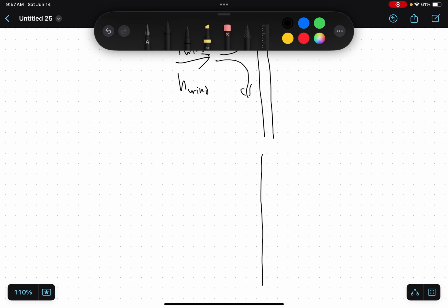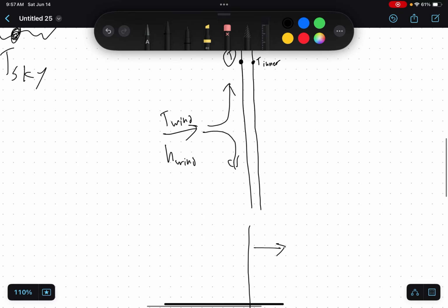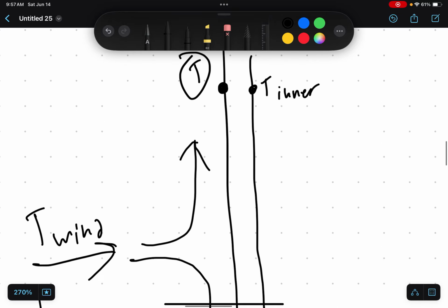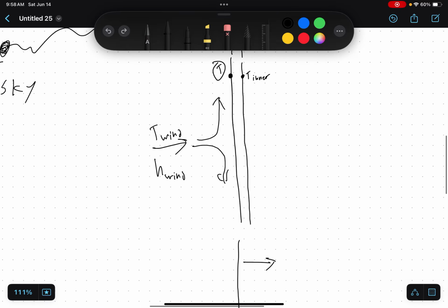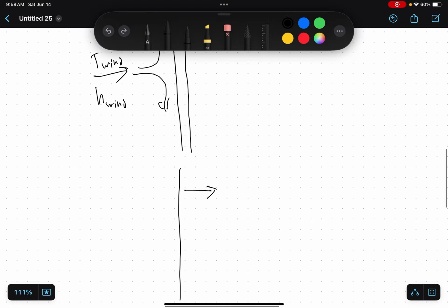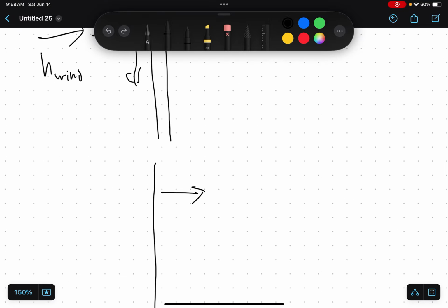So we've got a couple things entering and leaving. We start with conduction. So it's going from this point that way. Could be going the other way, but like I mentioned, it'll just turn out negative. So what is the equation for this? So the equation for heat, Q, or energy, is delta T over R total.